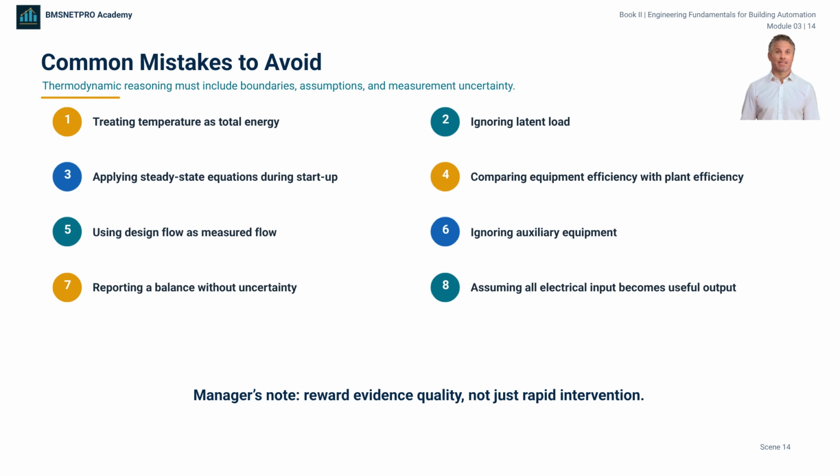Using design flow as measured flow is another major source of false conclusions. Design documents are not live measurements. Finally, never report an energy balance without acknowledging uncertainty. Airflow, water flow, humidity, and temperature measurements all have limits. Professional BAS work rewards evidence quality, not just fast intervention.